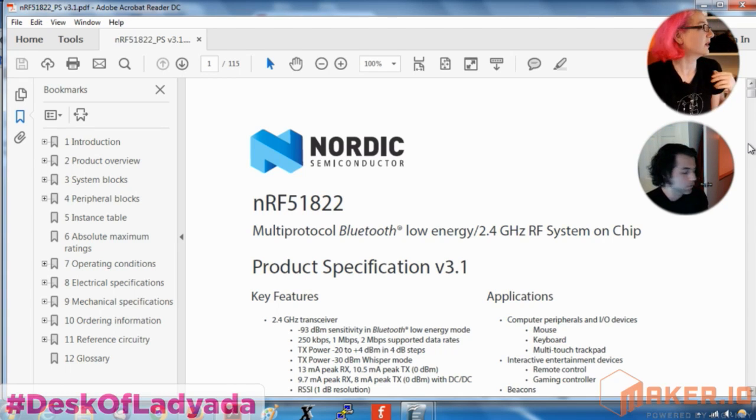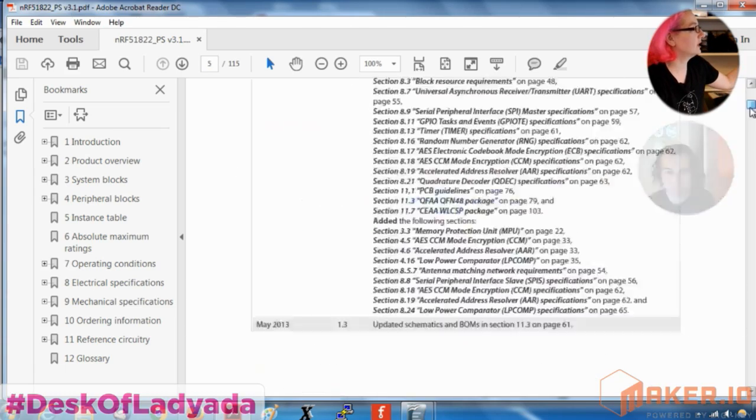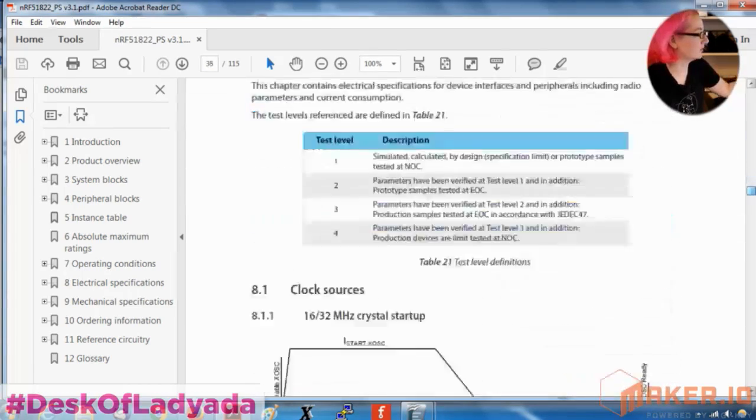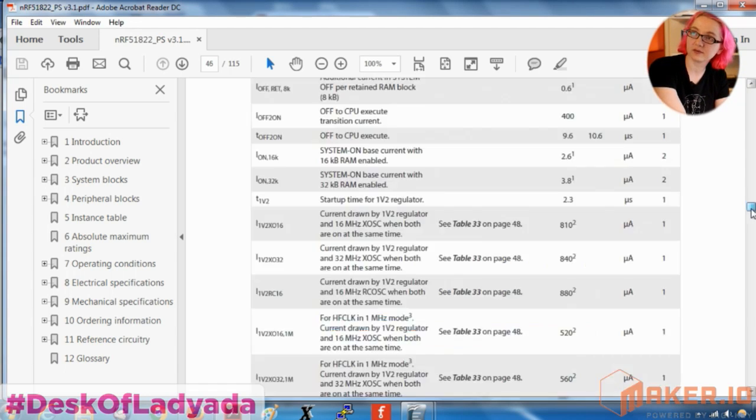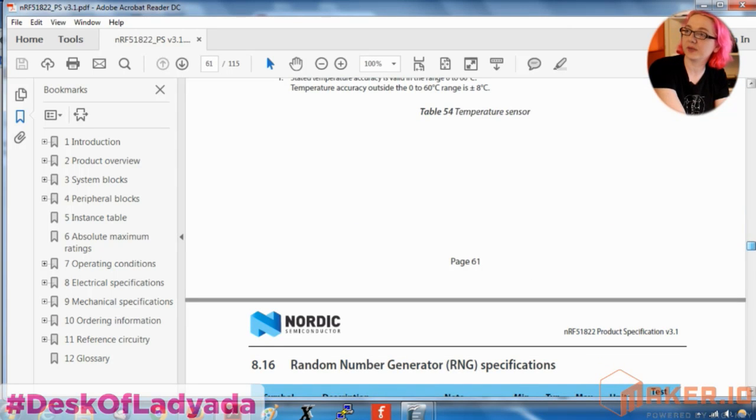So anyways, for example, here you can get the full data sheet for this chip, which actually is quite promising. If you can't get a data sheet for the chip you want to use, you might find it difficult to work with it, because it's almost certainly under NDA. Companies that require NDAs are usually used to working with very large companies, so you might not be able to get the attention you need. Working with companies that have open source tool chains means that there might be more of a community. So this is something to think about when you're deciding your chipset.